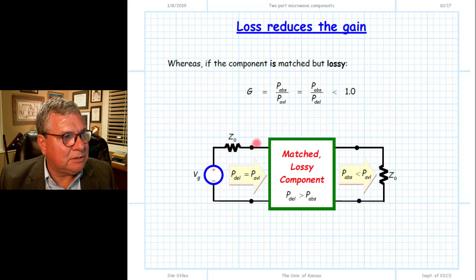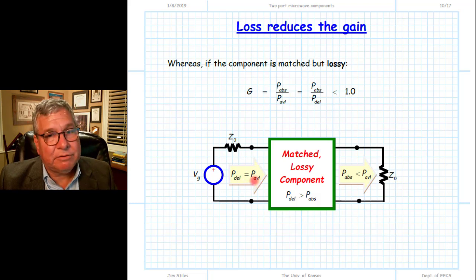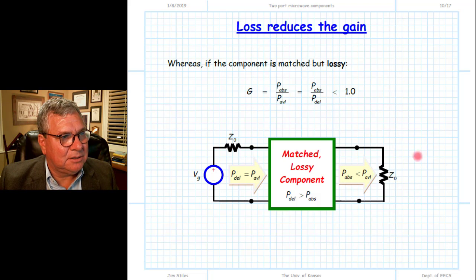as well. The equivalent circuit for all of this will be equal to Z0 if this is a matched device terminated in Z0. Because then the load of this matched source is a value numerically equal to Z0, all of the available power of the source will be delivered. Because this is a matched device terminated in a matched load, the available power of this source is going to be delivered. Delivered to what? Well, delivered to the input impedance of this structure, meaning that that delivered power is going to be absorbed by conservation of energy by this structure.